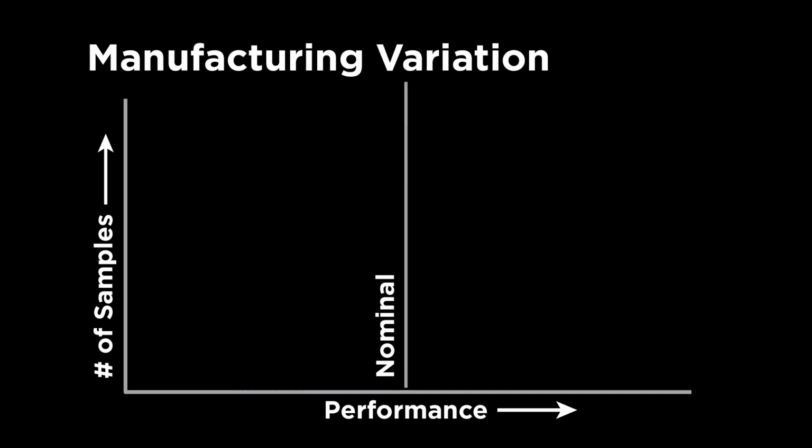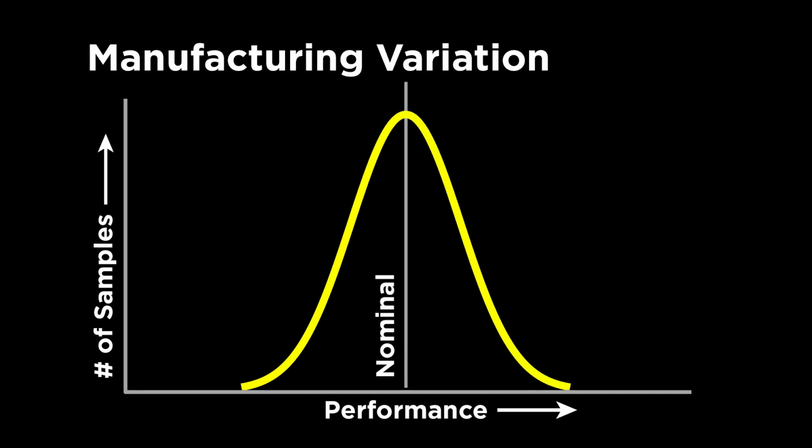Third, manufacturing variation. Even when manufacturers work hard to maintain quality and consistency throughout their operations, different manufacturers will find variations in compressor clearance volume, machining of parts, electric motor efficiencies, internal gas leaks, bearing alignments, and mechanical losses in friction surfaces. Again, these differences are minor, but they add up to as much as 1.5% in compressor capacity.